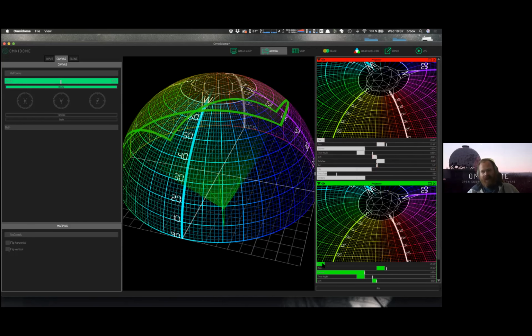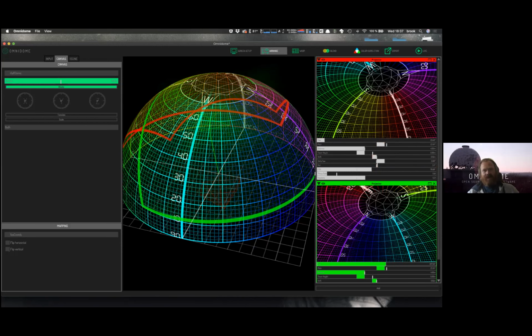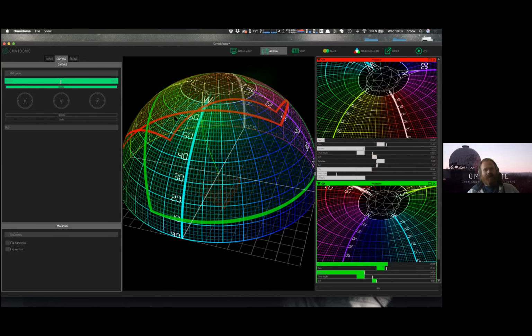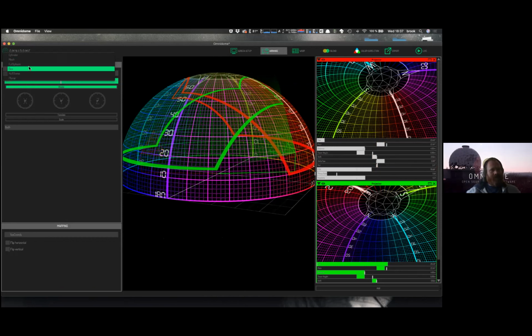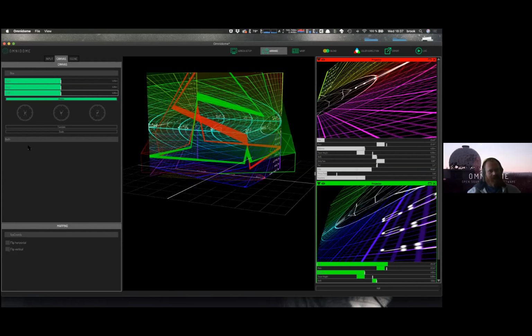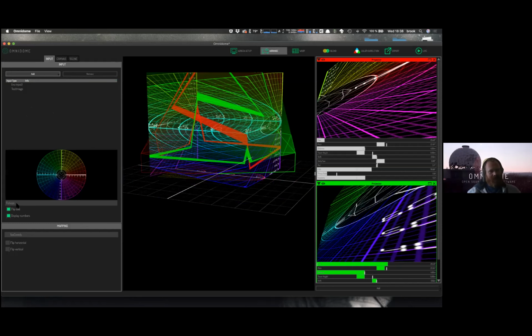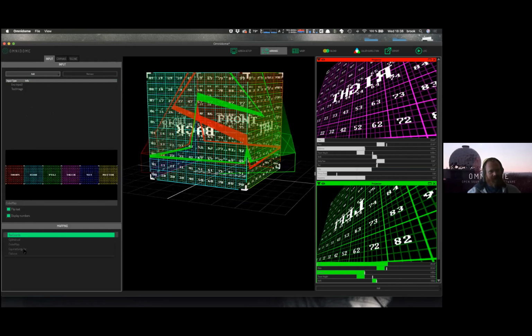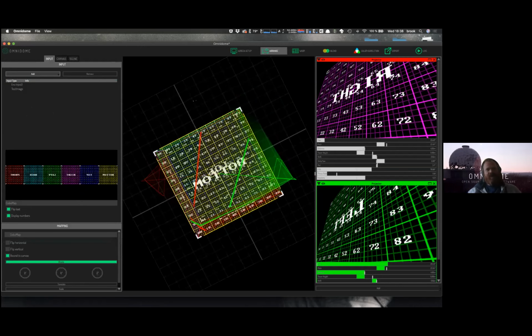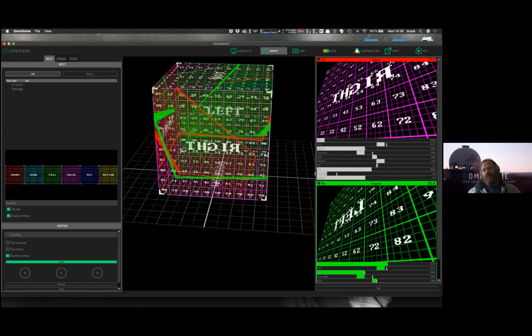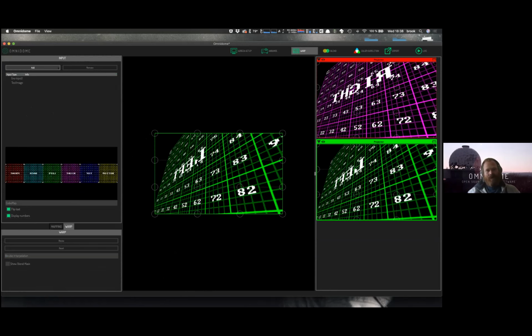And what you do is you just keep adding projectors until you've covered that space completely. Once you've covered that space completely, you have your projection mapping set up. And if you wanted to change that to something else, you could come in here, but then you also need to make sure that you pick the correct mapping type. So this would be using a cube map to map to a cube. And then these are what the individual projectors here on the right would actually see to be able to create that mapping. And then you have the warp grids.